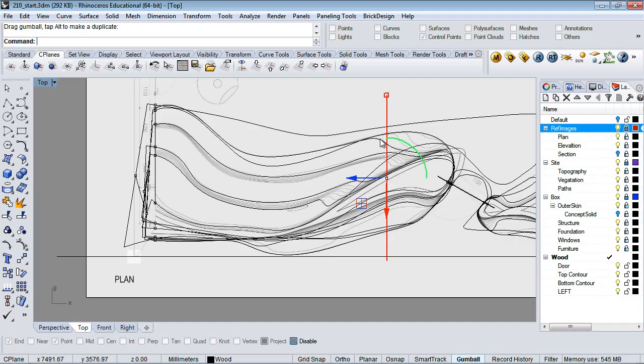Sometimes those cause some weird things because the curve is trying to navigate along that curve, and if you create a curve where it's already offset, so it's not in tangency to it, it's going to take that curve and do weird railroads, and sometimes that can give pinch points or strange geometry. So when you're doing cross-sectional curves, the best practice is to try to keep them perpendicular to the rail curves. Okay, that's the best practice. That's not always the case, and having a little bit off is not going to be a big deal.